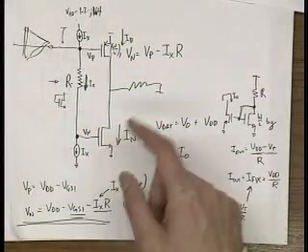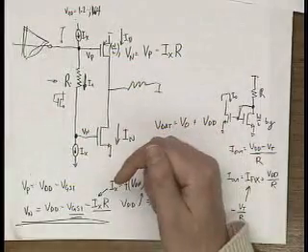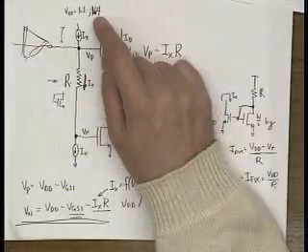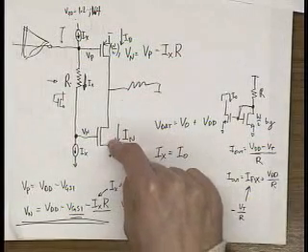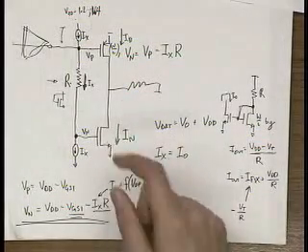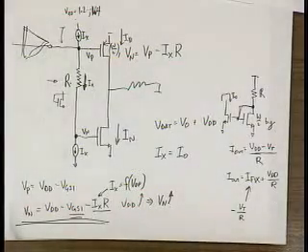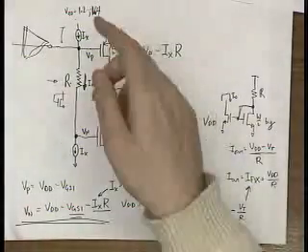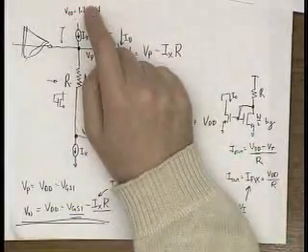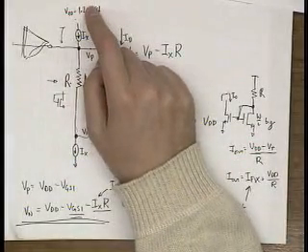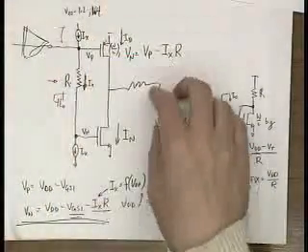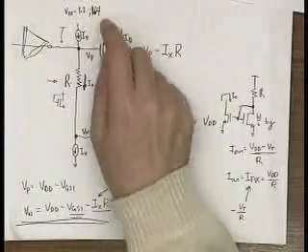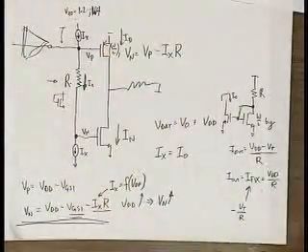So that's one design strategy. Fix it at 1.2, and then it'll be way off at 1.4. A second design strategy is make it such that at VDD equals 1.4, this current is exactly correct, in which case you'll be way off at 1.2. Now, the obvious middle ground is to design it such that it's spot on at 1.3 volt supply. Therefore, as you deviate from that, the exact output voltage will be correct neither at 1.2 or 1.4, but the error will be bounded. You'll be balancing your error.